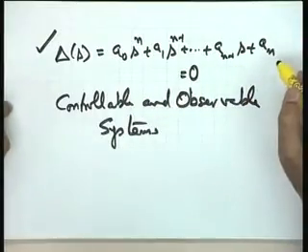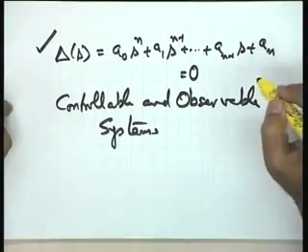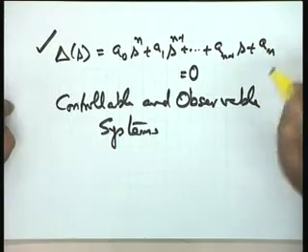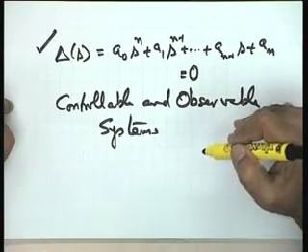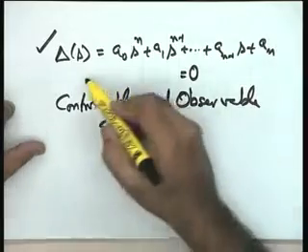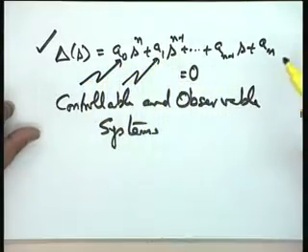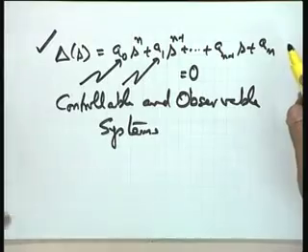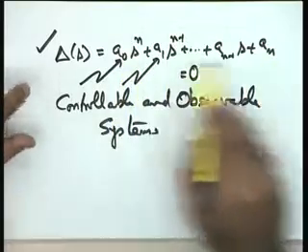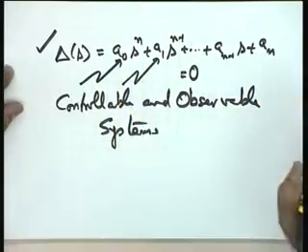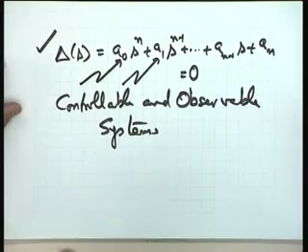But the point of further stability analysis is not referred to only absolute stability. We are going to use the criterion I am going to discuss in the design problem. For example, these coefficients A0, A1, An minus 1, An are functions of some of the physical parameters of the system. Let us say an amplifier gain K, a time constant of a sensor, or the torque constant of a motor. So, these are the coefficients of the characteristic polynomial. They are directly affected by the physical constants of the system.